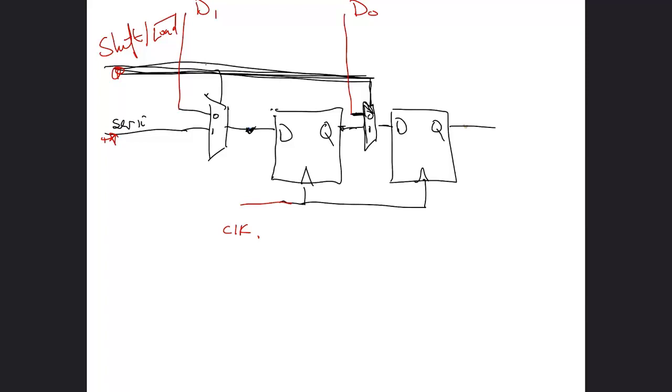Right. So everything that I've said now makes sense because there's only one more step. You can go and look at the lectures for this, but there's one more step where we say, do we want this thing to be enabled or not? But we don't really use that. We're actually just going to use this as if it's an enable line. While we're in state 0, just continue loading because we want to be ready to start shifting when the time comes. For each clock edge, we're loading stuff in this path here. And then as soon as the state changes, we change the state of this line with our state machine. We're changing this to a 1, which means whatever was loaded in the previous cycle, we're now going to start shifting it through. Does that answer your question?